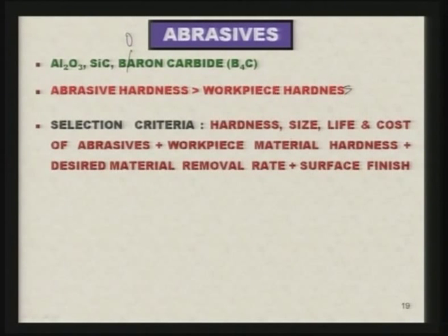Selection criteria: while selecting the abrasive, the following points should be taken care of: hardness, size of the abrasive, life of the abrasive and cost of the abrasive, plus the workpiece material hardness. This is very important. Workpiece material hardness should be known and taken into consideration.